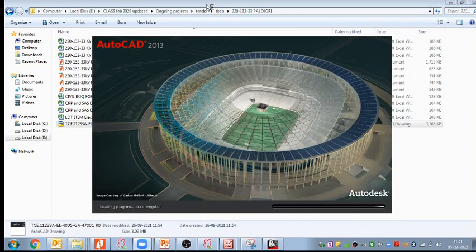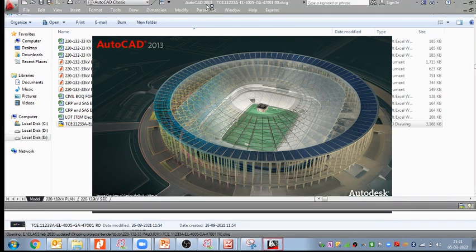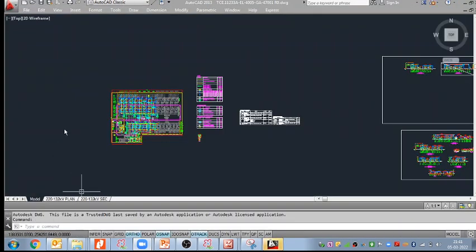50 meter is less, Rahmatullah. Do not take 50 meter. In case of substations, you go with 300 or 400 or 500 meter, around that. Okay, so if 30 VA is given as a burden, can we understand it? It is 30 VA per phase per core. Correct. Per phase, RYB 3 phase we have. So this 30 VA is per phase, and yes, it is per core.